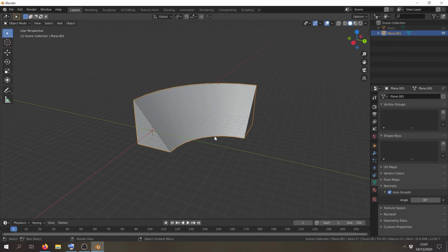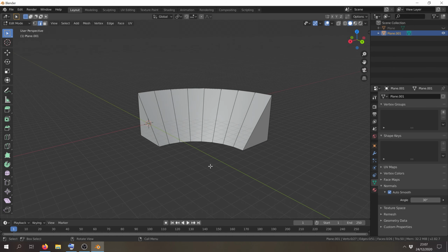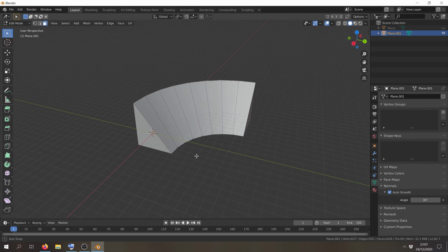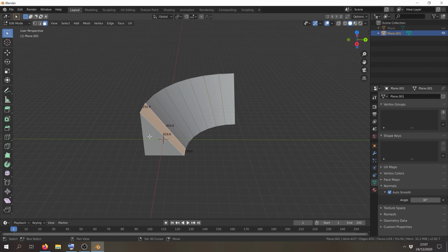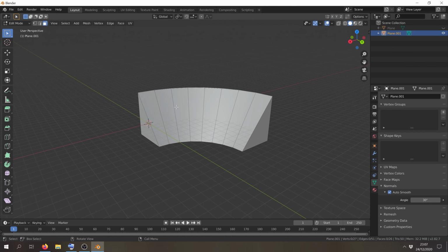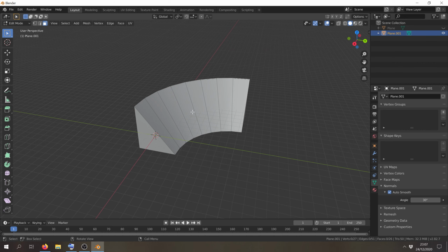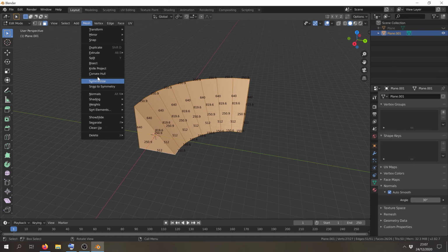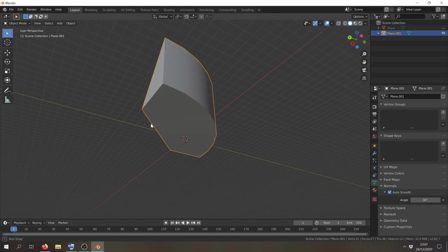Now there's a very specific way you have to create the physics mesh as opposed to what you do with the visible mesh. And what needs to happen is that these ramps need to have faces in between these. So each segment needs to basically be sealed up, for want of a better word. If you don't do that, what will happen is you'll make your model, and then this is what the physics mesh will actually look like.